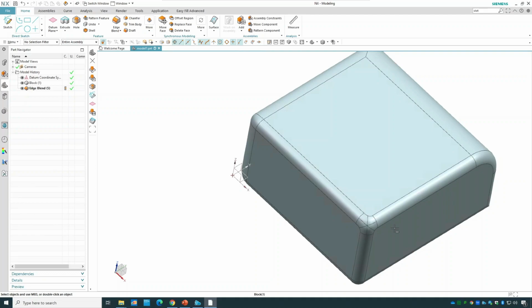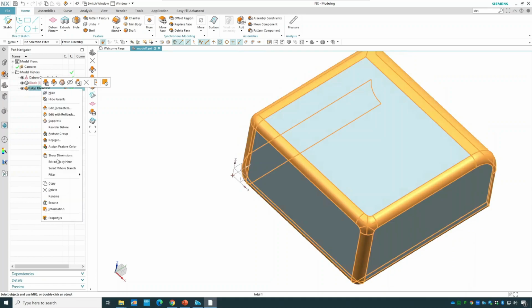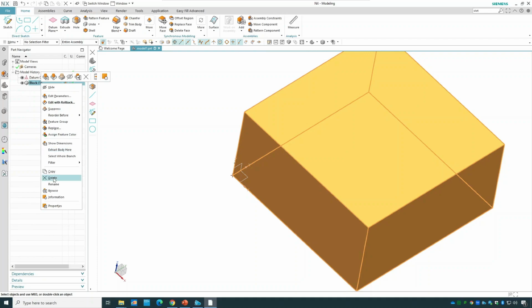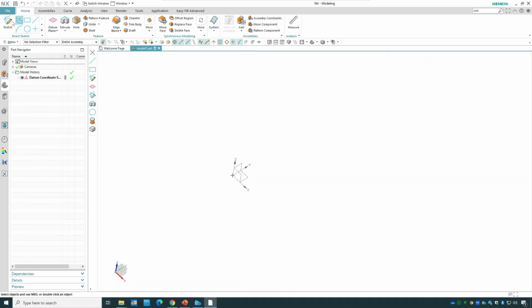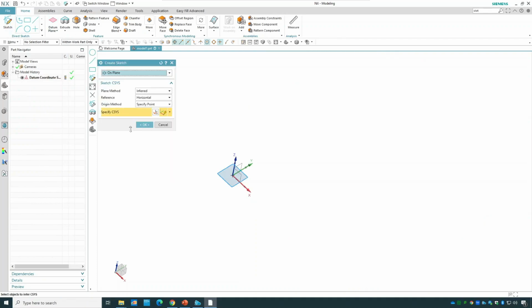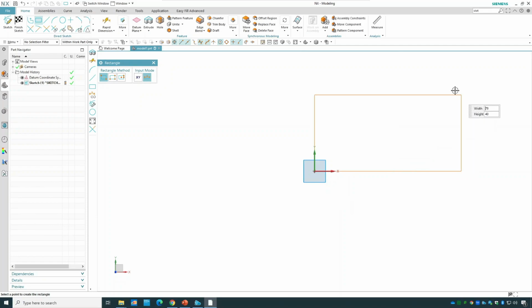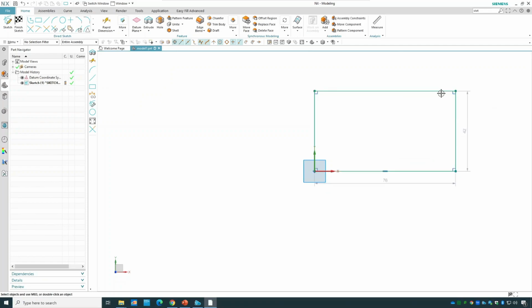Again, as you might ask, for example, with this key, what you could do is go to the 2D sketch, apply the fillet and then extrude it. So let me quickly show it to you. Let me get rid of that. And let me get rid of this block as well. So basically what I can do is go to the sketch, XY plane. Let me make the rectangle here. And then come out of the rectangle.